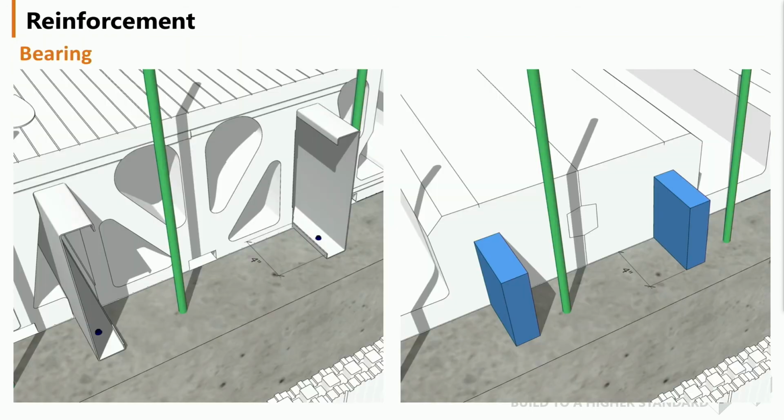The foam portion of Amdeck acts as a platform to work on and formwork to hold the rebar and the concrete. The wood or metal joists are designed to support temporary construction loads. The joists typically rest on the concrete, requiring minimum 4 inches of bearing. For the metal joists, we recommend screwing them down using the concrete screws.